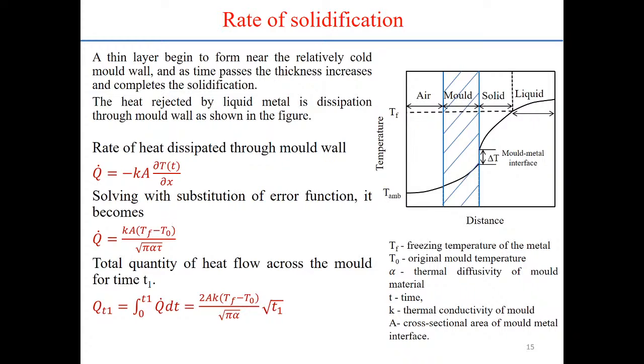Now we can also say something about solidification. Maybe you know that solidification time depends on the volume by area square, or some other formula you are using. But in this case we have explained the different solidification processes, and how we can estimate the solidification time based on the heat transfer mechanism, by looking into all the heat transfer mechanisms. But you have to relate it to the practical problem, what type of mold casting you are following. Accordingly, you have to use the principle of the heat transfer mechanism.